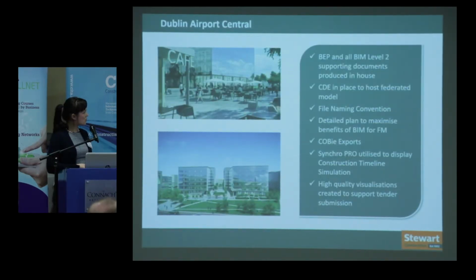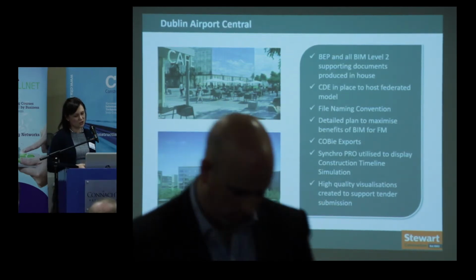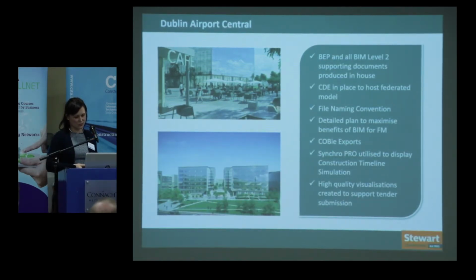And this project is a live project, so I will be focusing more on the tender stage, where we had to produce the BIM execution plan and all level 2 supporting documents in-house, put CDE in place to host federated model, and use file naming convention for all of the documents, and put detailed plan to maximize benefits of BIM for FM, COBie exports, and Synchro Pro was utilized to display timeline simulation, and high quality visualizations produced to support tender submission.